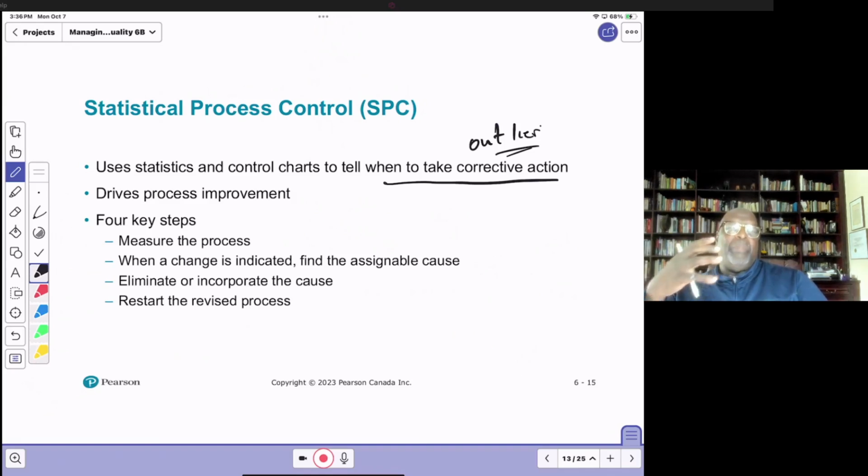So you're usually hypothesizing that the process is in control, or the process is out of control. So when you now take the data and you plot it and you see an outlier, that tells you that you are outside of the limits and therefore the process is out of control and you should shut it down, do an inspection, improve it, and then restart it. Okay?